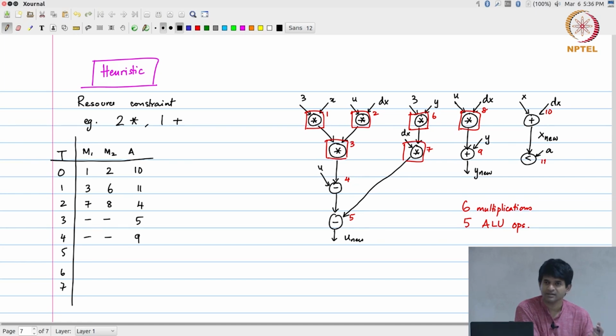The adders then definitely will not be, or rather the ALU will definitely not be, because the ALU only has 5 operations on it. But more importantly, if you think about it, what you will see is that even that may not work out completely in practice, because there are other dependencies. So unless you are able to finish the ALU operations and then the multiplication operations and then push the ALU operations correspondingly immediately after that, you may not be able to hit 6 cycles latency also.